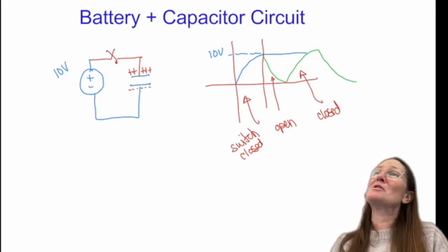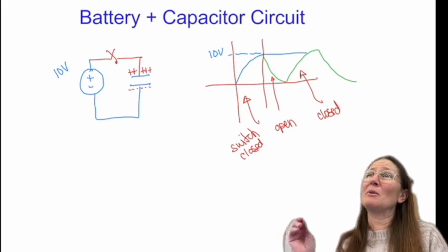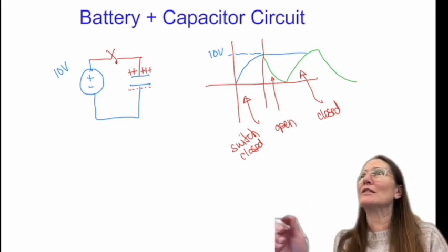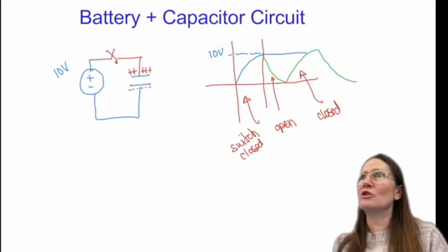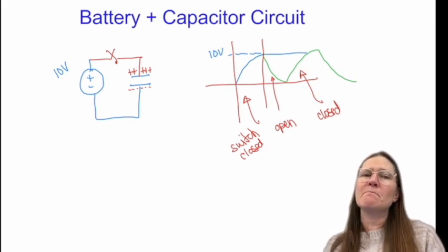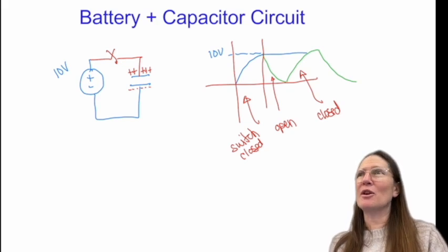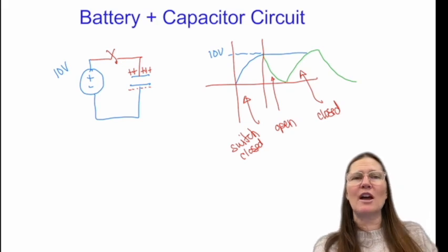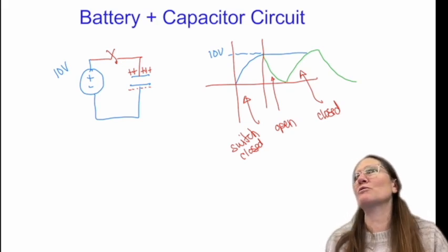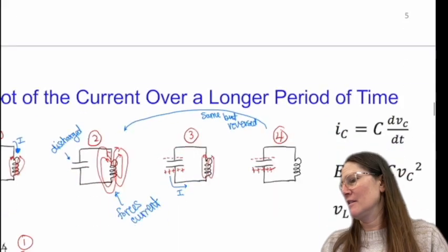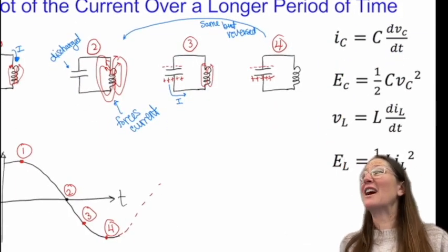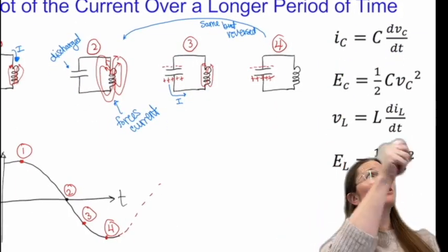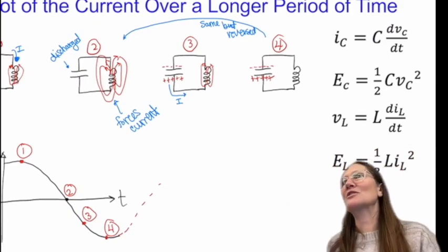So an RC with a really small value is going to be really quick. It will charge and discharge really quickly. But it's hard to model that when you don't know the parasitic resistance. So we usually don't analyze it the same way we did with the general form equation. That's why I'm talking about what is actually happening physically when you don't have a resistor in there.